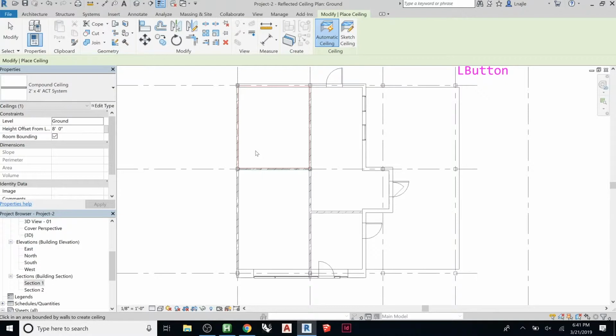If you think of like a desk or a door, all of those types of families, you have different ways of controlling them, and you can save them outside of your Revit project and then reuse them. But the walls, the floors, ceilings, those you have to model in place, and then on the next project you would have to draw them again. The family type you can save, but the actual wall itself is not going to be the same physical wall. Does that make sense? The Revit component families are like blocks that we were using in CAD, where you can always just grab the same block.